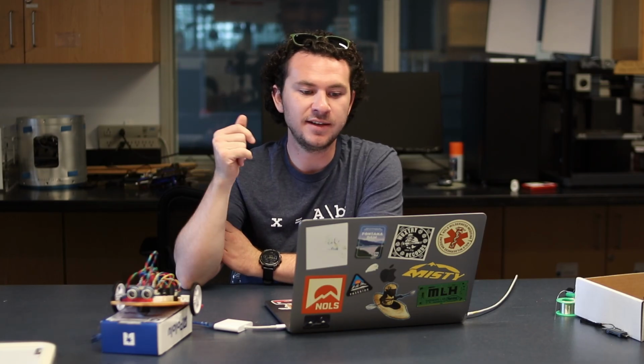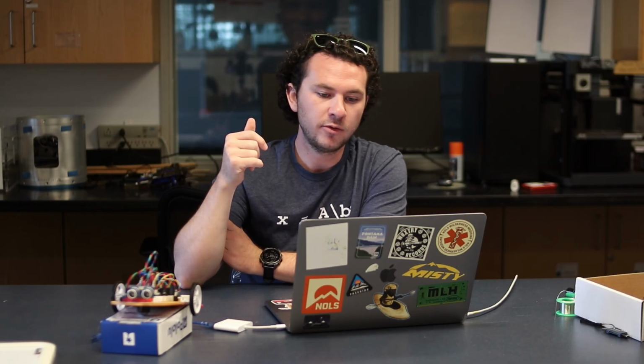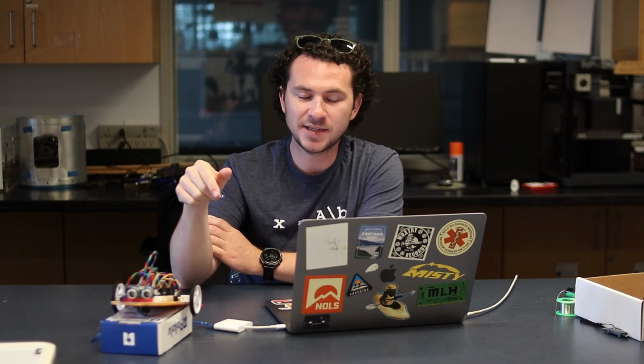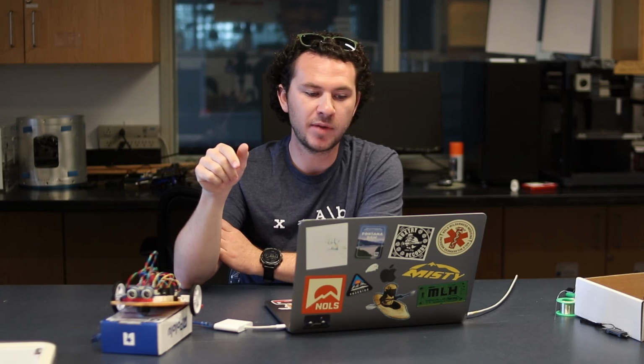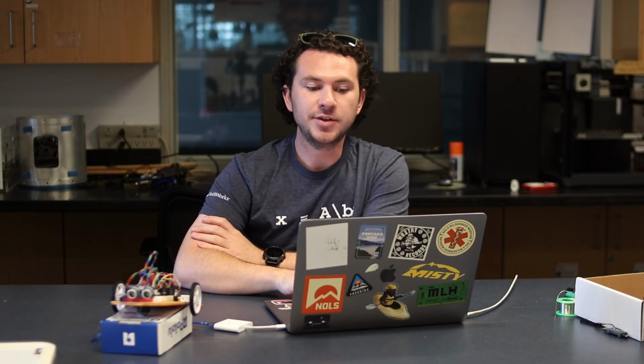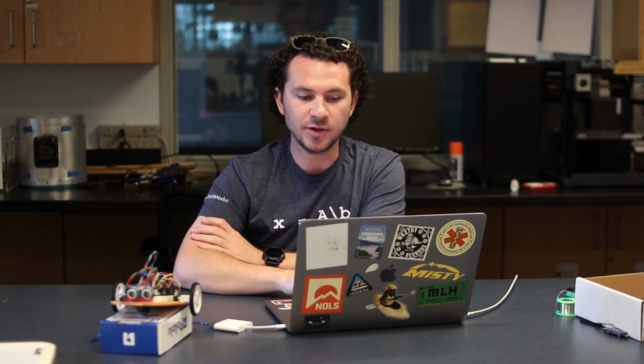We also set that serial baud rate to 115,200. When we open the serial monitor to view data, we need to specify the baud rate in a little drop-down menu on the right side of the monitor. Otherwise, everything we see will be gibberish. Next, we're going to try to start I2C communication with our IMU chip.